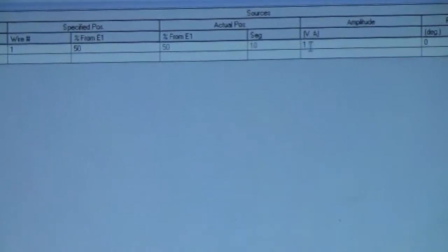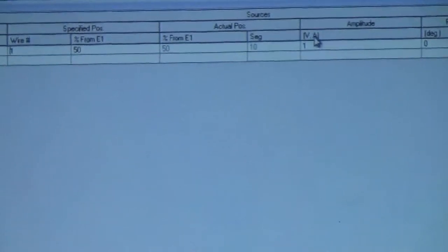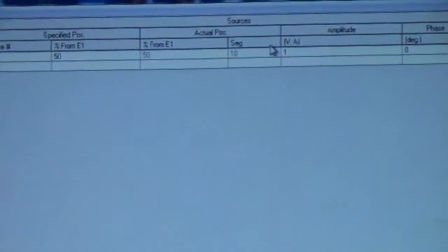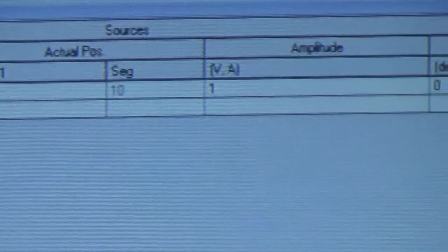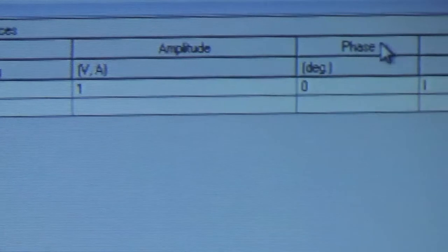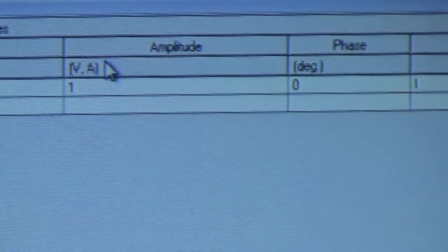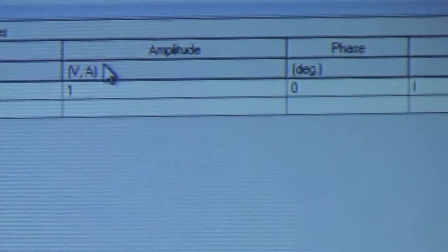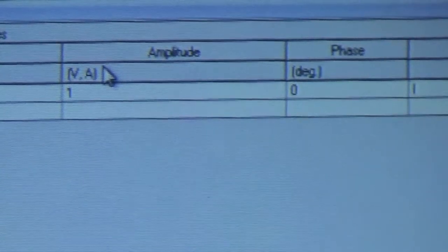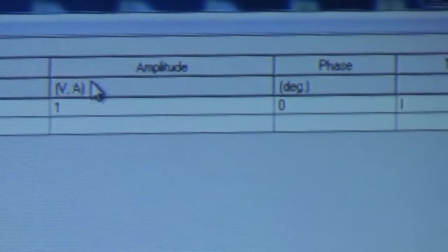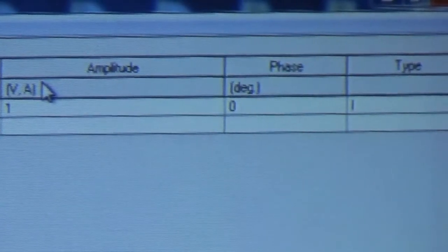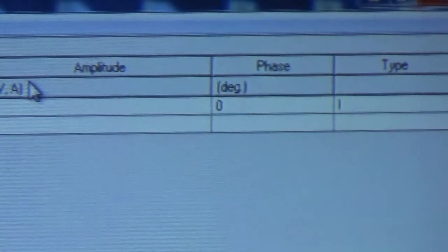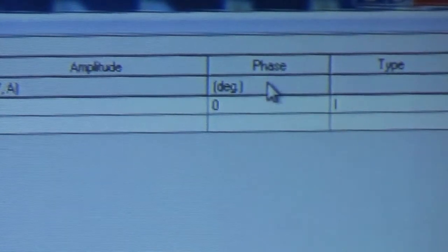The type of source, there's voltage sources, there's current sources. Typically, you stay with a current source, because that's what center fed dipole will use. There's different reasons that you would use the voltage, or there's split feeds if you have 2 segments that come together at a 90-degree angle, things like that. And like I said, this thing can do a lot, but just for doing the basics is what I'm going to show you tonight.